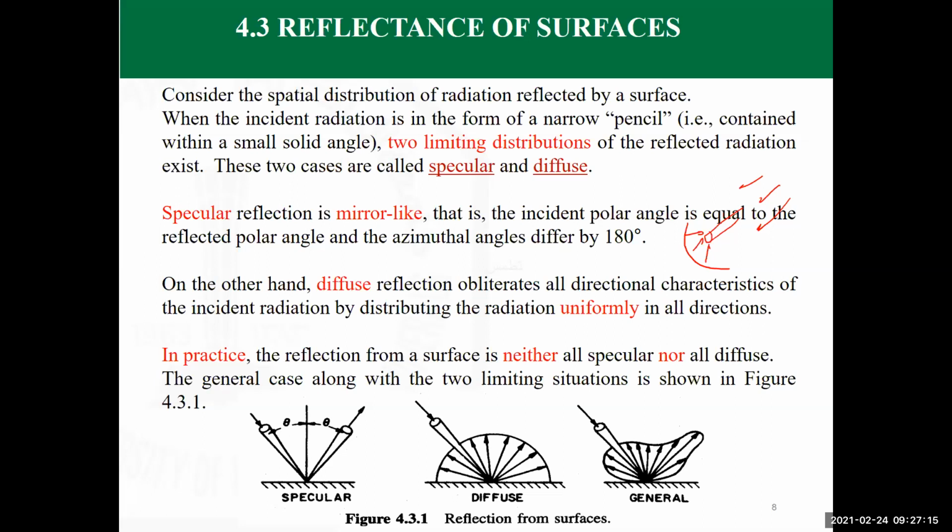a tremendous increase in the heat transfer. Sometimes what you have inside the tubes is heat transfer oil that can be heated to temperatures of 300 to 400 degrees centigrade, sometimes more. So you can use it to generate steam, and then you have a Rankine cycle, but without a boiler. A Rankine cycle where you can get steam. The steam can expand in a turbine and give work. Then you have a condenser, you have a pump, but at the end, instead of the boiler, you have this tracking system for heating the water into steam.